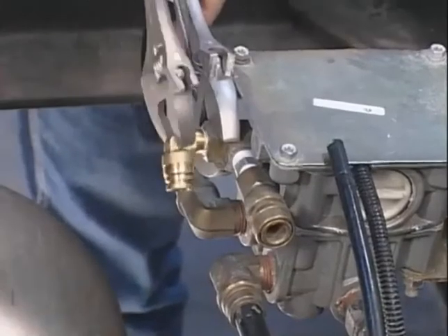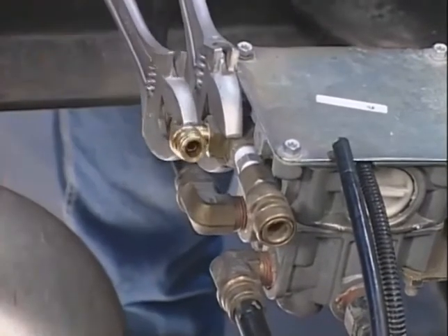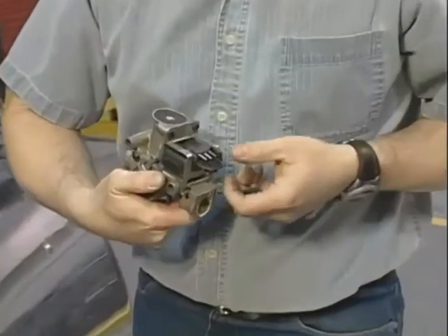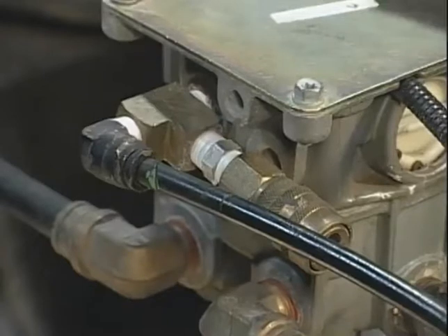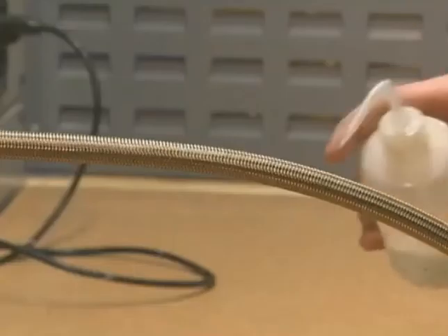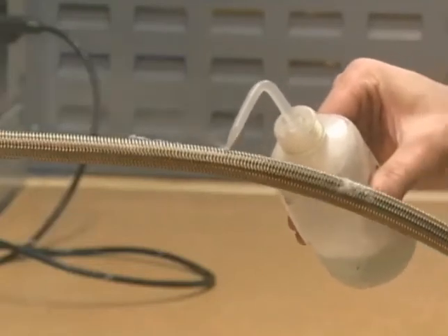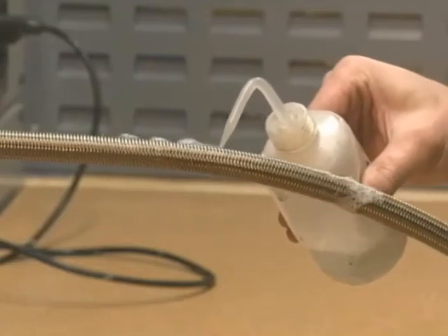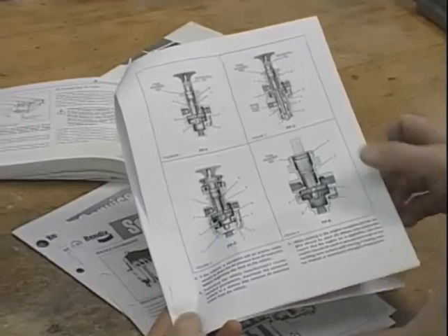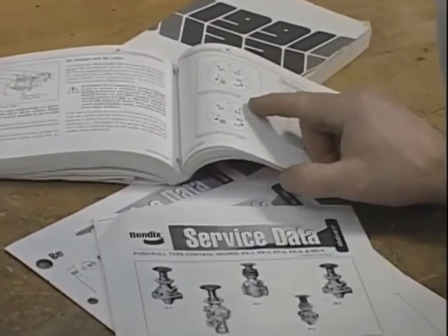We'll start with some basic rules of thumb. First, if it's loose, tighten it. If it's obviously cracked, broken, or misinstalled, repair or replace it. Repair or replace leaking tubing or hoses. Inspect braided steel Teflon air hoses using a soap solution, as leaks or cracks in these lines are hard to see or hear. And if you're unsure about something, always refer to the service data sheets and vehicle service manual.